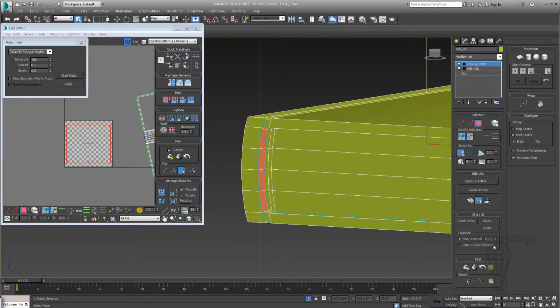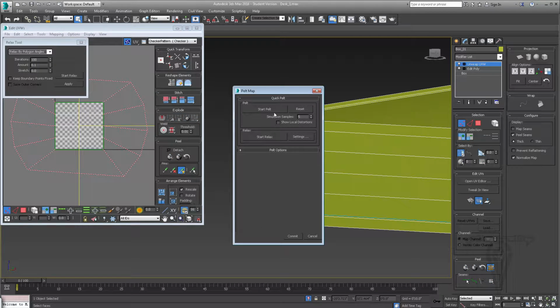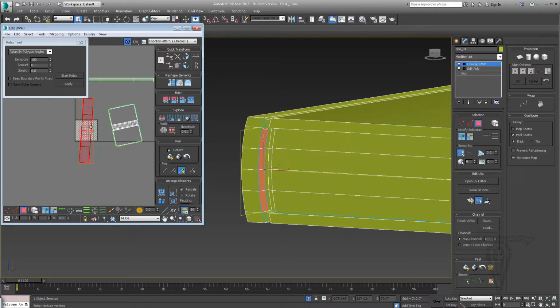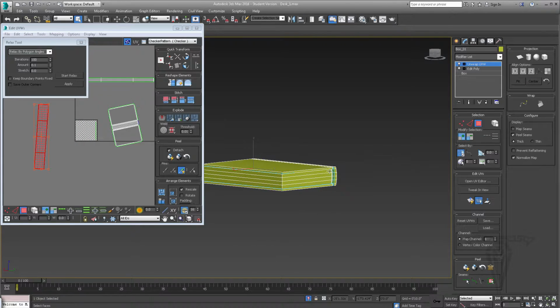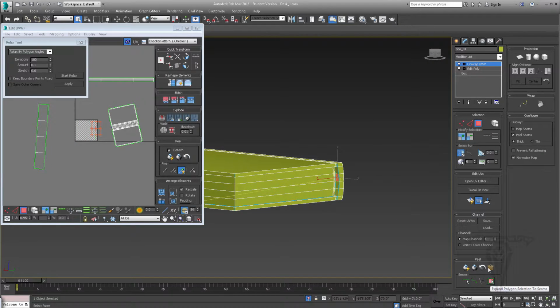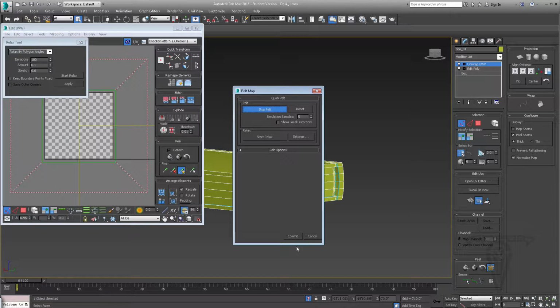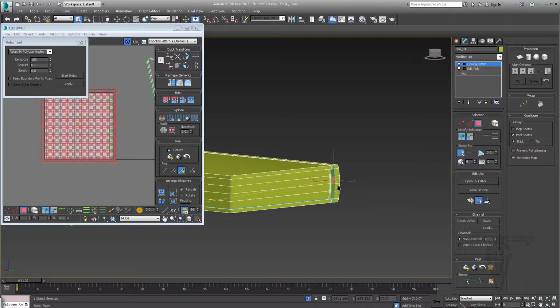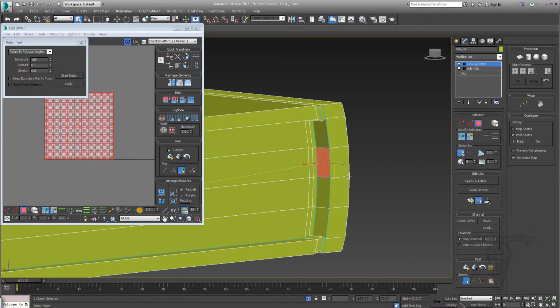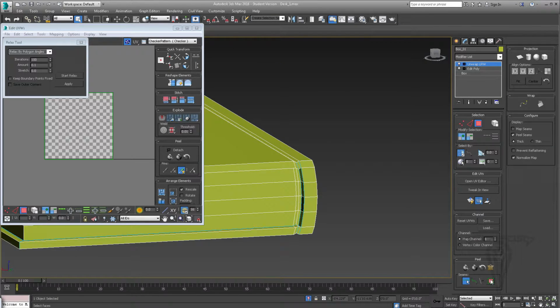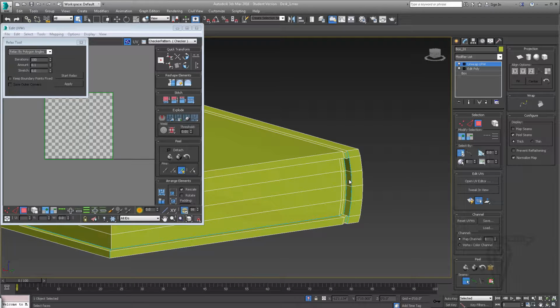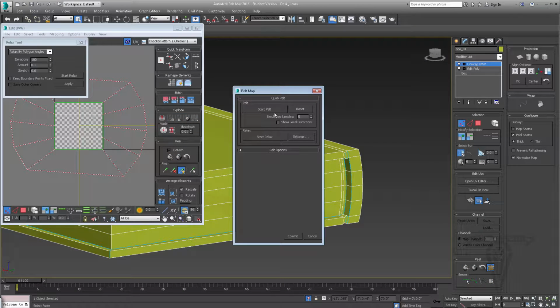And what do we have left? We have these edges here. I'll just pelt both, or pelt one at a time. Pelt, start pelt, commit, start relax, drag it off to the side. And last but not least, pelt, start pelt, commit. Whoops, I'm going to undo that. Because I accidentally did that, it created some extra seams in here, so I need to get rid of them. I'm going to hold down Alt and click. There we go. So now I can go to polygon again. Actually, I need to turn off seams. Expand pelt, start pelt.